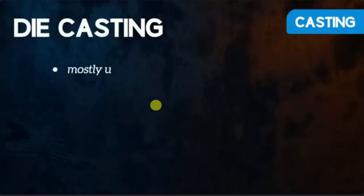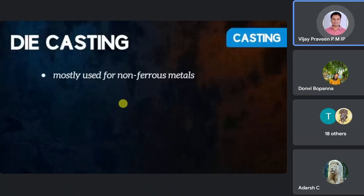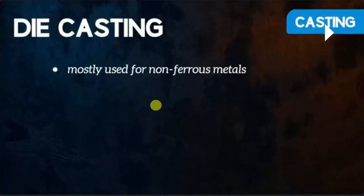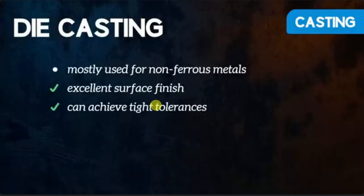Die casting is mostly used for non-ferrous metals like aluminum. Very important: die casting is not meant for ferrous material. It is used for non-ferrous material like aluminum, which has a low melting temperature. It provides an excellent surface finish and can achieve very tight tolerances, but startup costs tend to be high. So the advantages of die casting are an excellent surface finish, and close tolerances can be achieved, depending on what type of dies we are using.